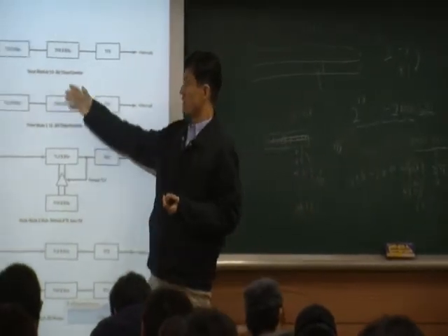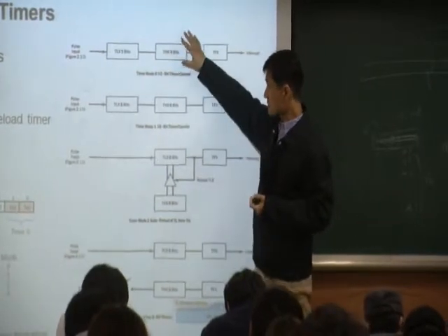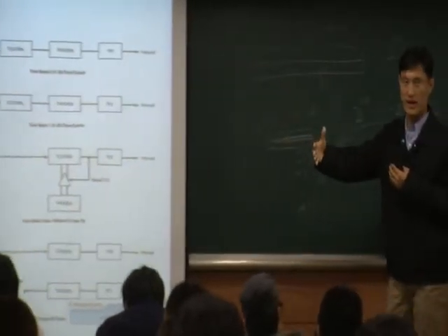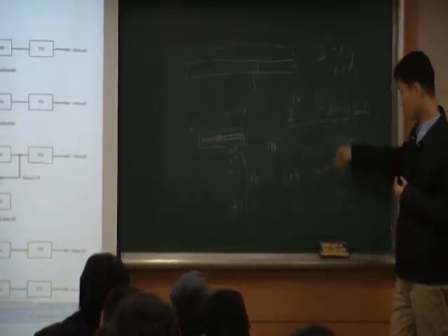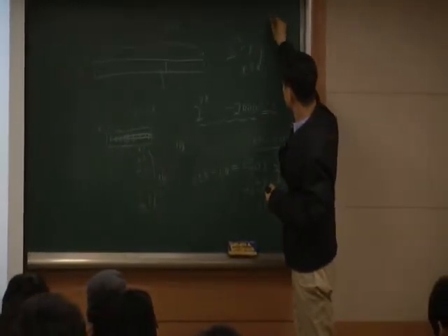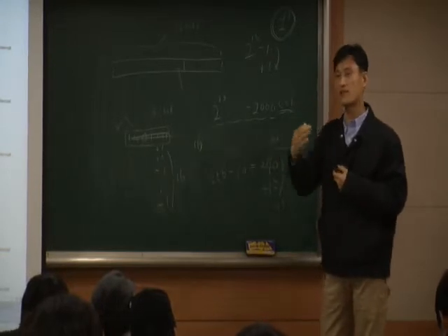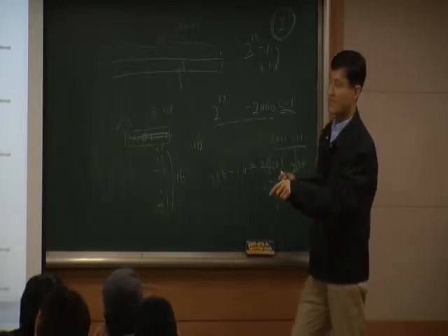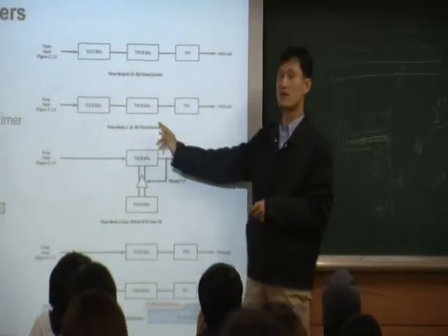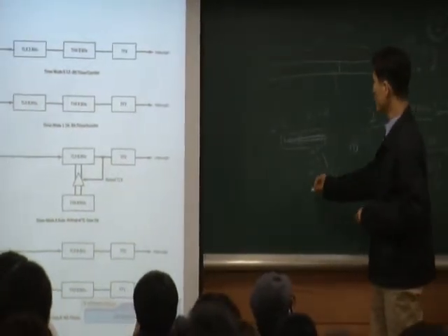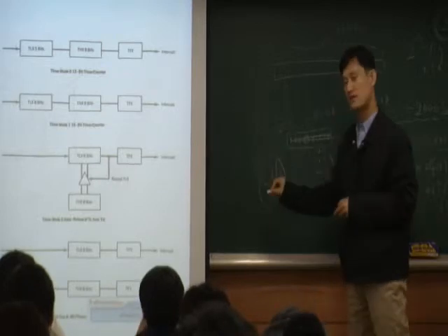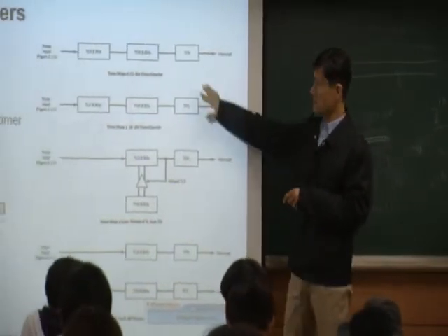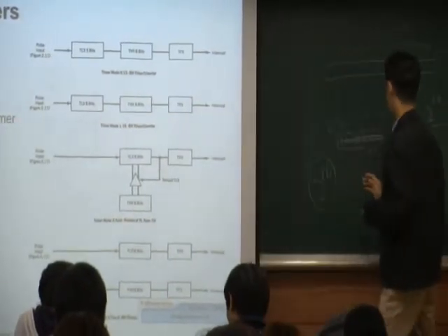Simply, okay? The difference between these is that this is a smaller timer. We have a 13-bit. So the maximum pulses you can count is this much, actually 2 to the 13. This is the maximum number of pulses you can count with this timer. But this timer is a 16-bit, 8-bit here, 8-bit here. So therefore, with this timer, you can count more pulses, 2 to the 16 pulses. Right? So simply the size is different. Okay? So this is really easy to understand.